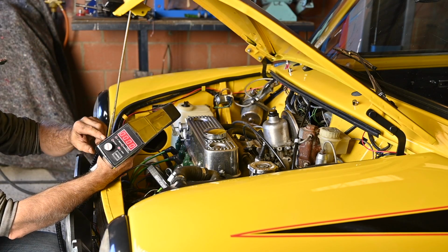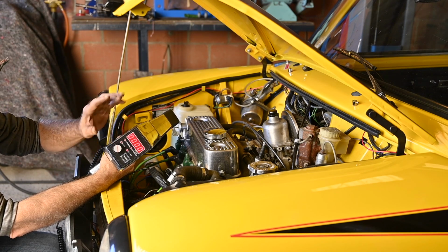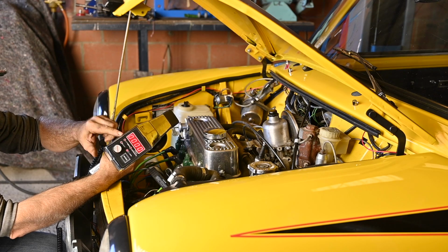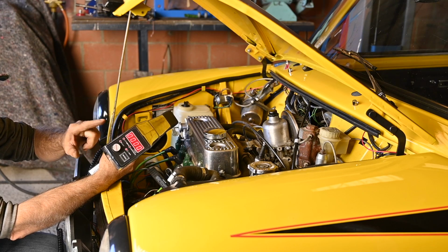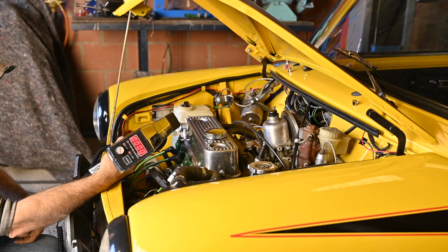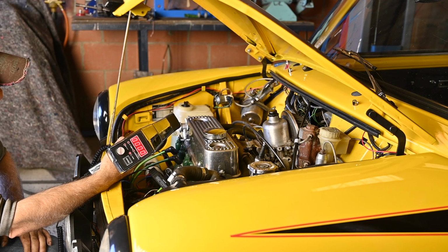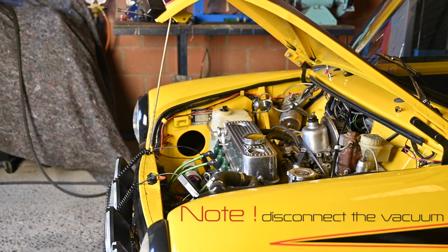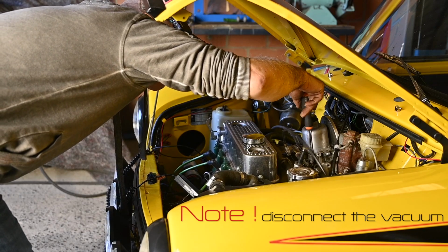Now on this strobe light I have something we call advance, so I can set the advance myself, so it will calculate it. So if I set my advance to 10 degrees on this device, then it will still flash at top dead center. So this is a nice feature of this strobe light. So you might want to get a strobe light like this, because it's going to come in very handy once we start testing the dynamic advance. So let me start the engine and then see where the setting is at this moment in time. So make sure that the engine is running at sufficient idle speed.